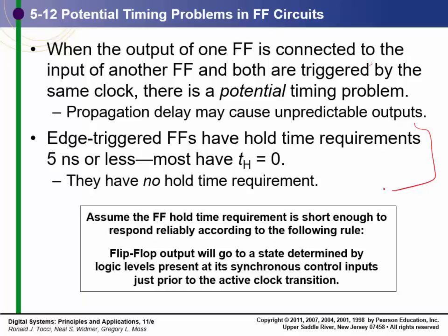After the clock edge, the data doesn't have to be there very long, if at all, is what this slide is saying. So if you have an older technology that does have a hold time, you can get into a problem. Where you get into the problem is that the propagation delay is more than the hold time.